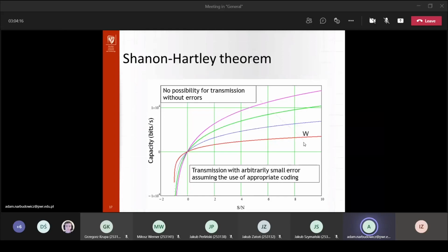So for example, nowadays, compared to the initial Wi-Fi standards, there is a scheme called channel aggregation, where each Wi-Fi channel typically has 20 megahertz. However, if you need higher channel capacity, you can combine two 20 megahertz channels into one 40 megahertz channel, right? So this is exactly this principle here. By increasing the bandwidth, you increase your channel capacity, which allows you to transmit more information without error.